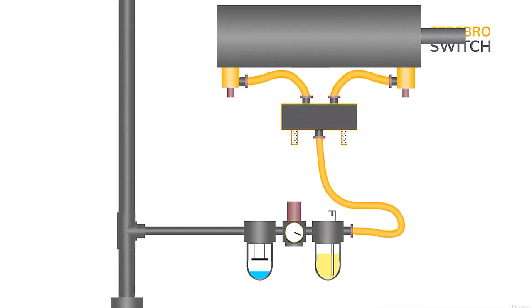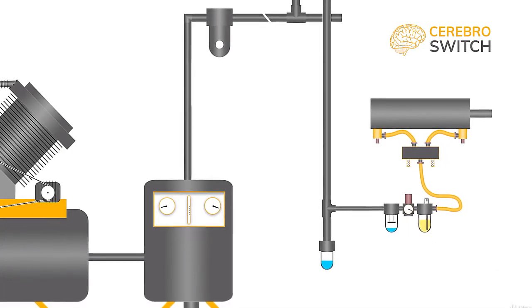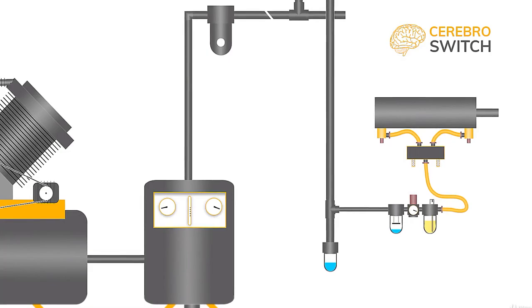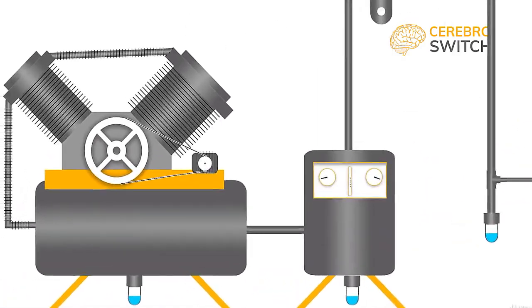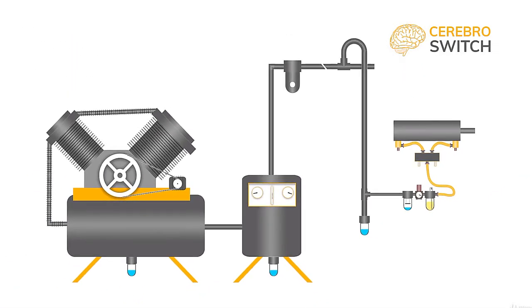At this point, our pneumatic air is already pre-filtered by the main line filter, which is present at the centralized preparation stage. Most of the water is also taken out up to this point, by eliminating it when condensed in an air tank, tube network, and in heat exchangers. The oil is usually sticking to the filter element in regular air filters, but if there is a need for more, manufacturers have developed specialized filter elements.